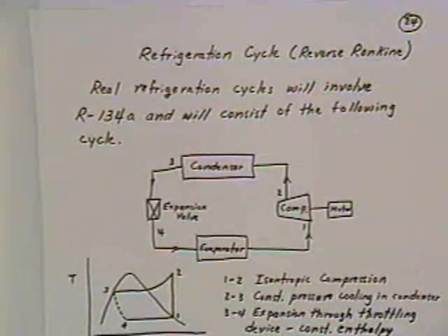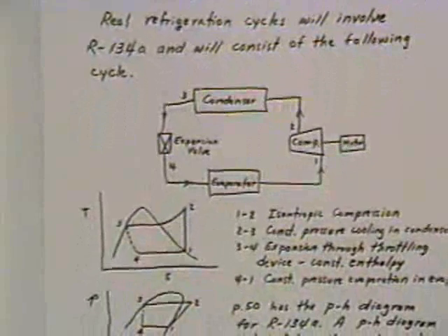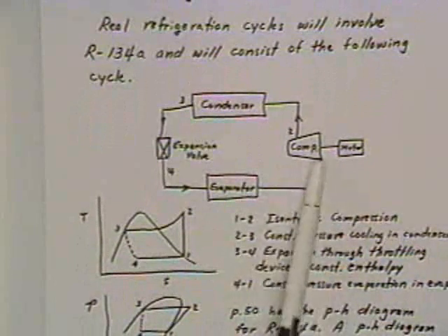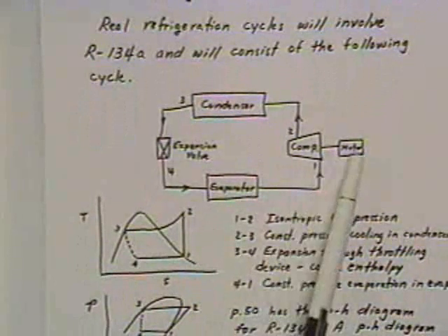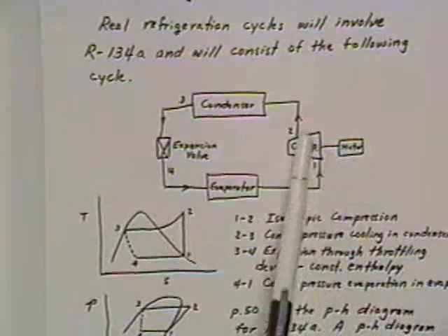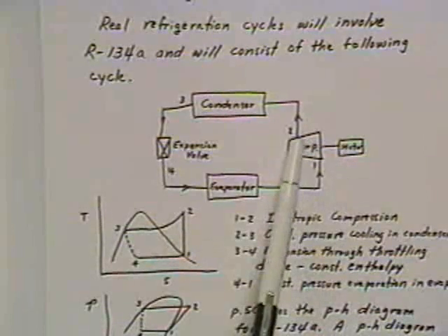or some of the less environmentally friendly refrigerants. And so when you go through the Rankine cycle here, or the reverse Rankine cycle for the refrigeration cycle, we'll be using R134A as our refrigerant. So let's go ahead, and I've sketched in for a refrigeration cycle here all the relevant points for just a simple cycle. Of course, you've got the compressor that's driven by a motor, so it's a work input device into the compressor. State 1 to state 2 is typically assumed as an isentropic compression.